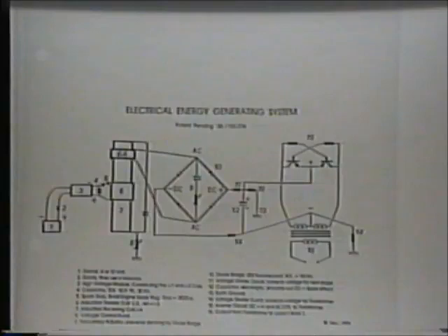There's a spark gap which helps control the energy level that's passing. The spacing on the spark gap there will control the energy level of the energy that's going into your L1 coil. Then, of course, number 7 is your L2 coil, and number 6A up there is Tesla's 3rd coil.